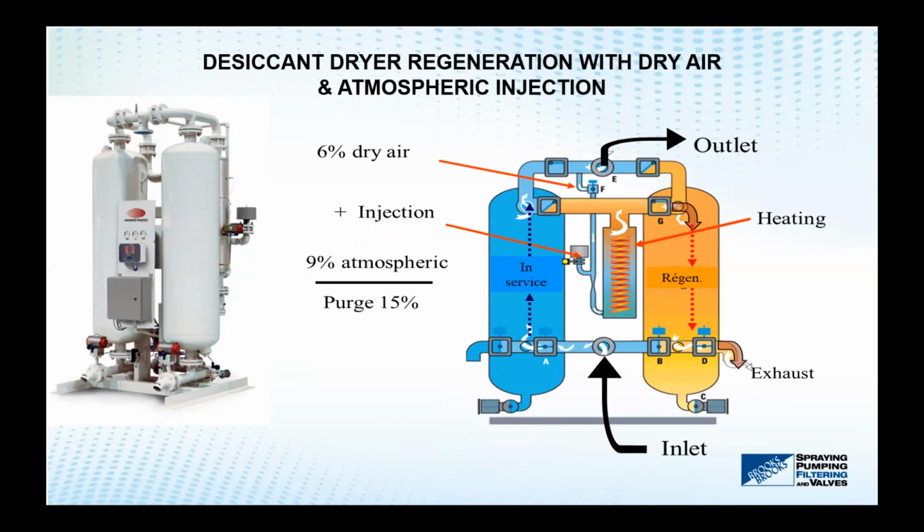The bottom line is, every time a customer comes to us with an application that's, let's say, over 1,000 SCFM, we start evaluating all these different dryers based on what the customer has as a resource. Can they afford the 15% purge, and what size is the system? But in the bottom line, it's all about what the energy savings could be. How much does the electricity cost to operate this heater during a year? And being as these systems often last in plants 20 or more years, this becomes very important if you're saving significant amounts of energy every year.